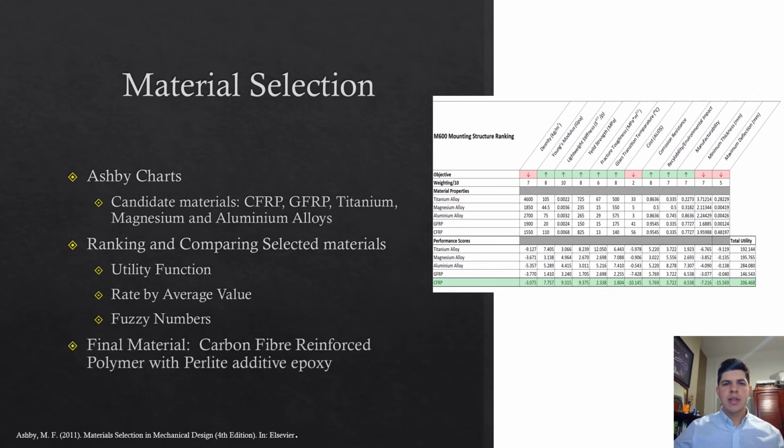The highest performing material for each component was carbon fibre reinforced polymer, and to improve the fracture toughness and its operating temperature, a perlite additive epoxy will also be incorporated to ensure system performance and to meet the constraints outlined in the project brief.